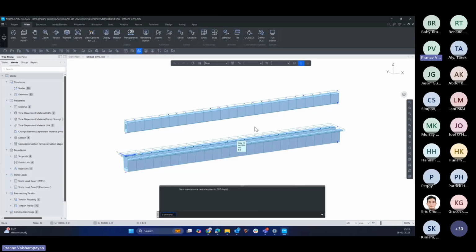So the Debonding Made Easy plugin is used to define debonding lengths in our model. In any scenario, when we have a project, we usually take a simple beam and then try out various debonding equations, various debonding options with a simple beam. Once we find our appropriate debonding lengths, which also satisfy the transfer state check, then we apply that in a full scale model. The idea is similar over here.